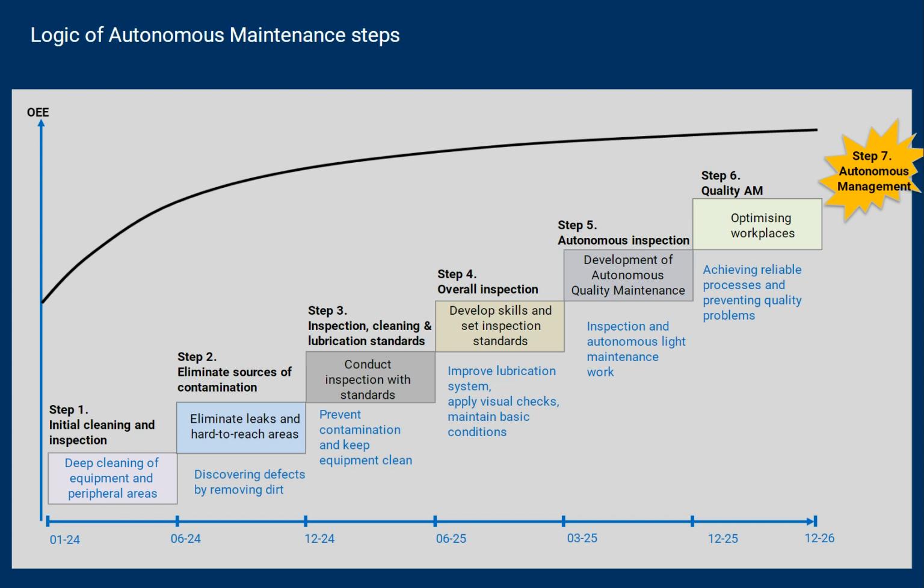The first phase of the Autonomous Maintenance Development Program consists of steps 1, 2, and 3. It is the starting point for autonomous maintenance, and also for all TPM activities. This phase comprises activities designed to restore the equipment's basic and original conditions, while providing operators with a solid understanding of autonomous workplace management. This is achieved by establishing appropriate methods for cleaning, inspecting, adjusting, and lubricating. As a result of this phase, an efficient system is implemented to ensure the maintenance of basic equipment conditions and optimal operation. In the following, we will analyze how these 3 steps of the pillar work.